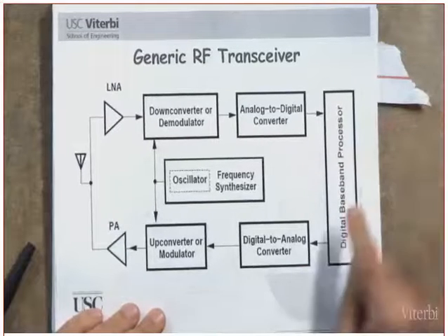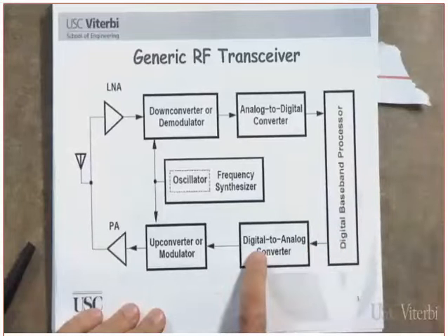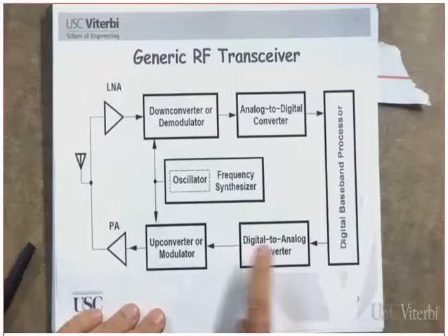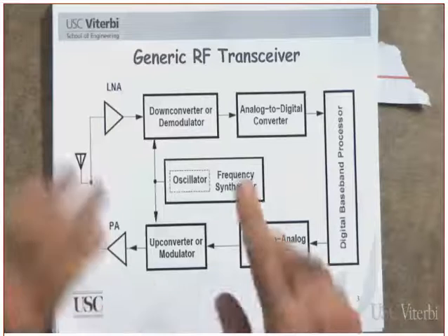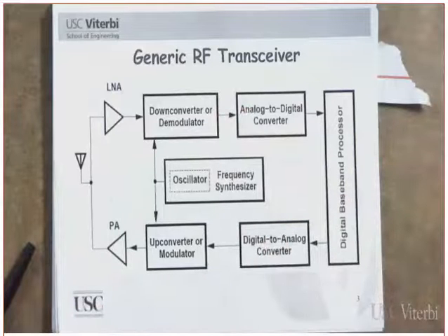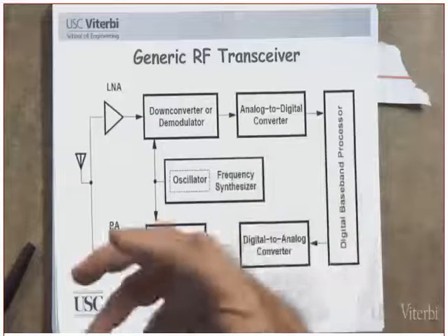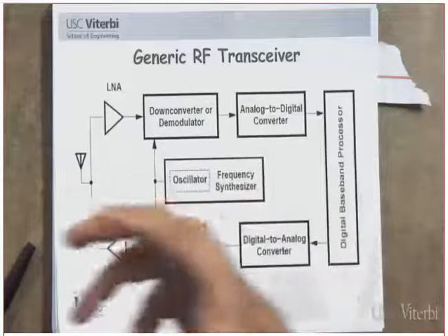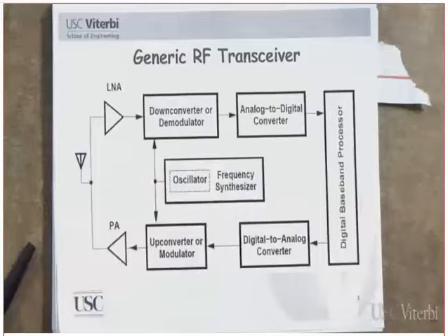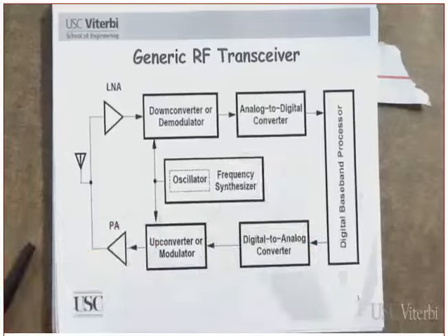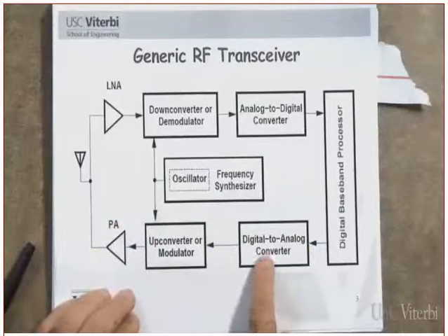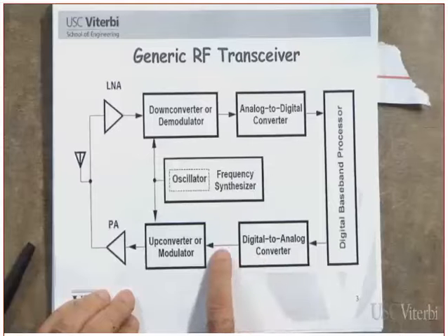So the processor here generates the digital signal. This is a what? A DAC, converting it from a digital to an analog signal. And again, as I told you, for the purpose of what? Smoothing the edges so that the spectrum occupancy becomes what? Becomes more what? More compact, rather than keep getting that sinc function. Remember the sinc function? Instead of getting this sinc function, you try to what? You try to shape. Later on, by the way, we will also refer to this and the filter afterward. We call it what? Pulse shaping.